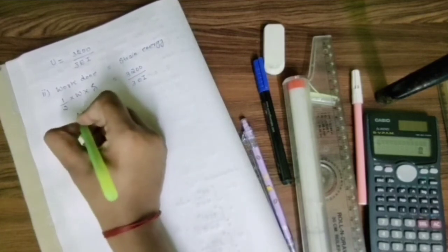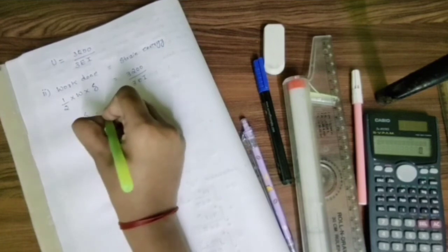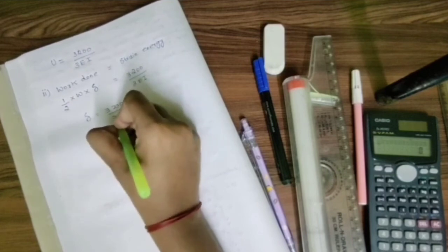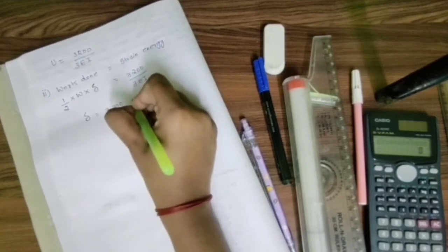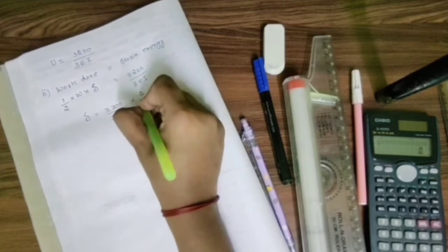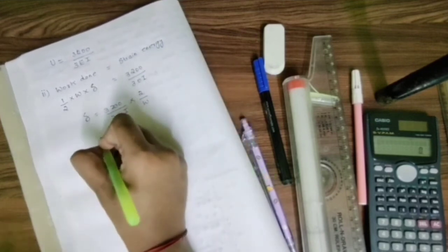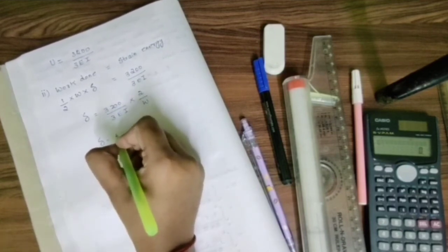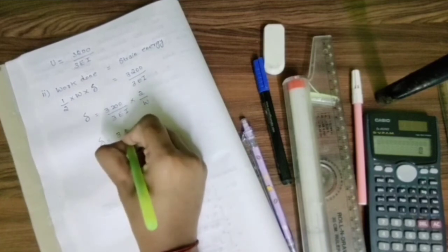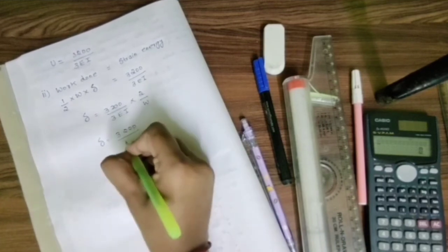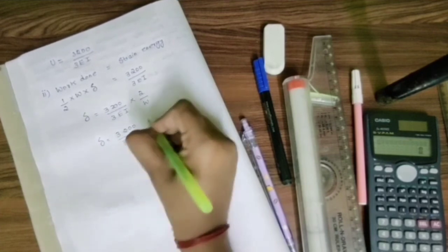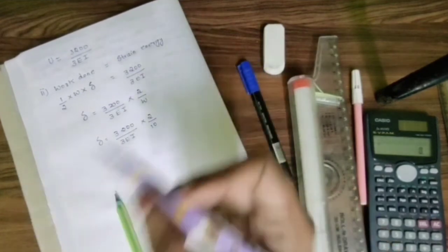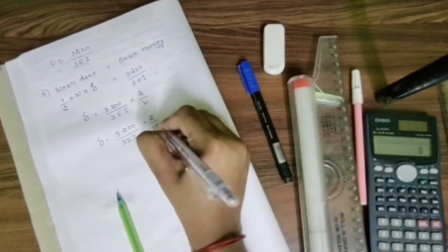Now in this step we need to calculate deflection. So keeping deflection, that is del at one side and moving everything to the right side, which will be 3200 divided by 3 EI into 2 divided by W. As it is moving on to the right part, it will be in reverse manner. We know that it is just a basic thing, basic maths. So 3200 divided by 3 EI into 2 divided by 10. It is because W is equal to 10 kilonewton. They have given it in the question.